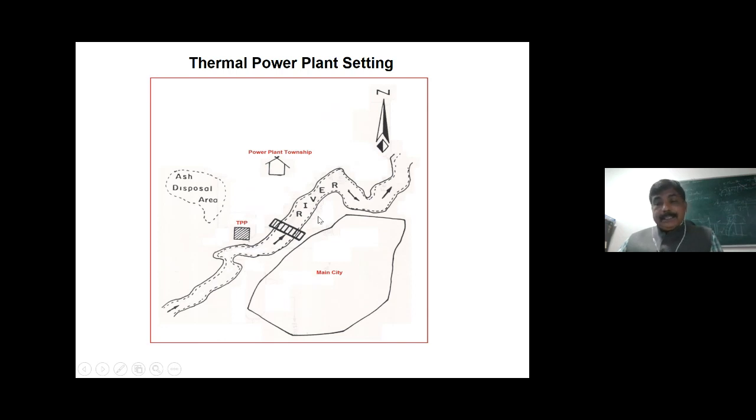Coal, water and air. Why air? It's abundantly available because for fire it uses air, and coal is for fuel. And why water? Because after the generation of electricity, a large amount of heat needs to be thrown out. How to throw it out? The hot steam after the turbine, we cannot throw it away because it is actually high quality water. Now that water we need to re-inject into